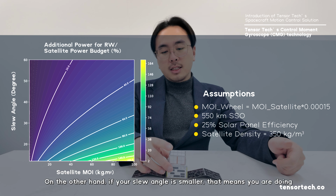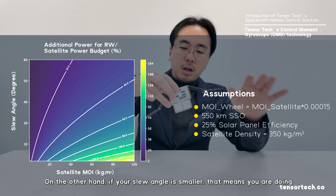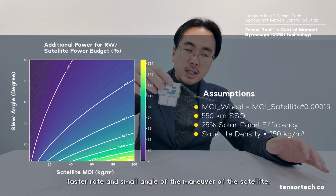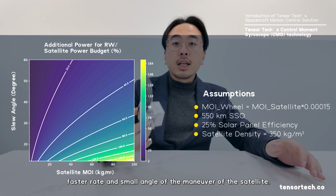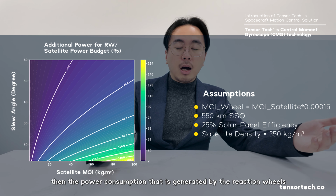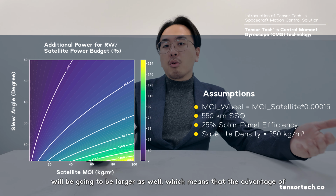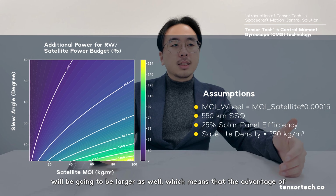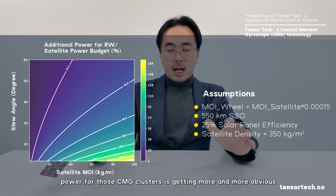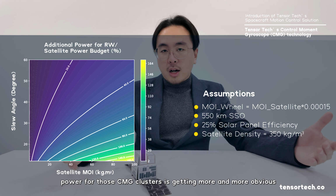On the other hand, if your slew angle is smaller, meaning you are doing faster rate and smaller angle maneuvering of the satellite, then the power consumption generated by the reaction wheel will be larger as well, which means the power advantage of CMG clusters gets more and more obvious in those use case scenarios.